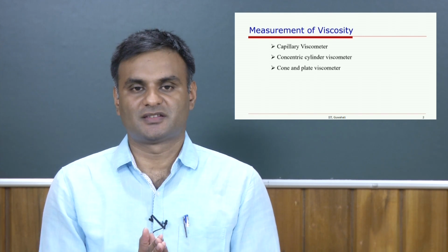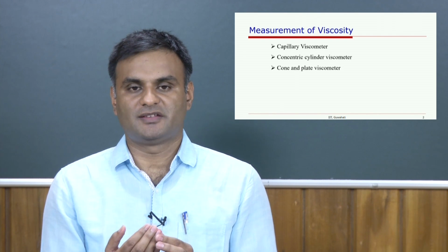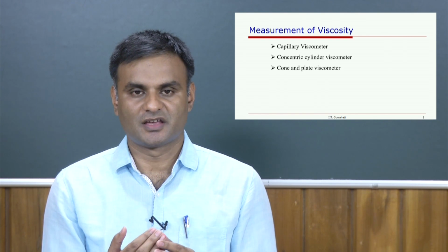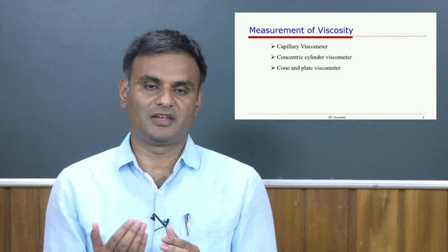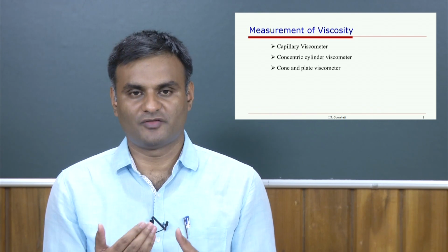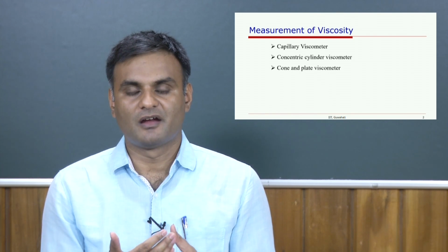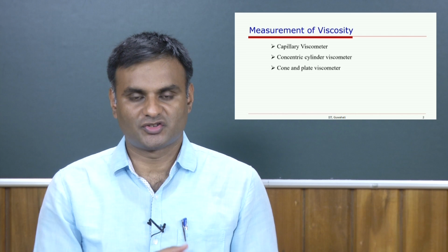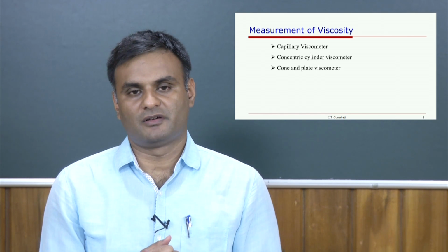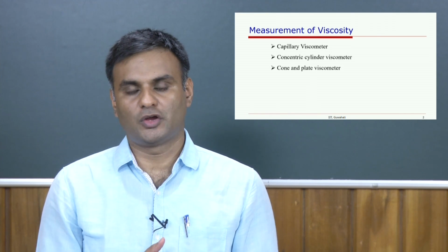By doing this, one can calculate the shear stress being exerted on the inner cylinder, and from the ratio of shear stress and shear rate, one can measure the viscosity of the fluid.